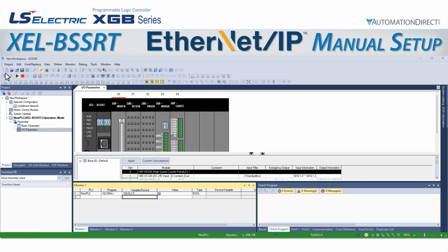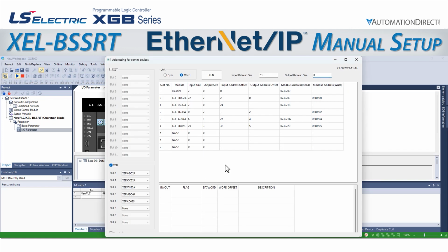Let's add that to the monitor window so we can see when the module turns it on and off. We can also go into monitor mode, and we see that the output point is currently off. Let's pull up our data addressing tool again. We see that the TN32A will be at an output address offset of 2. Note that the first address offset is 0, so address offset 2 will be the third address.